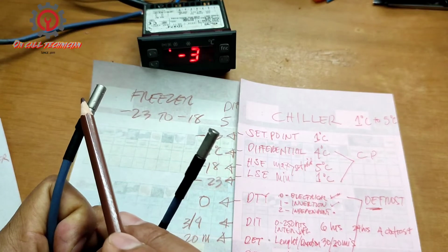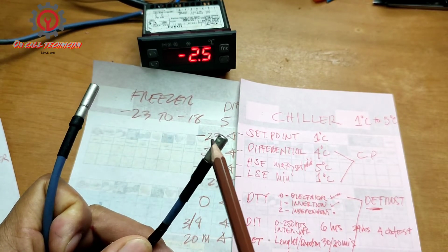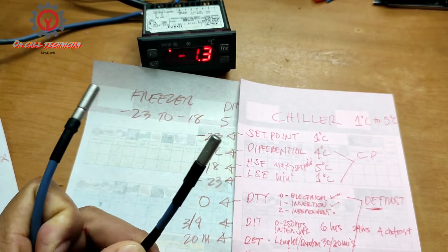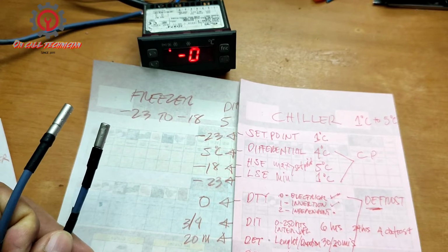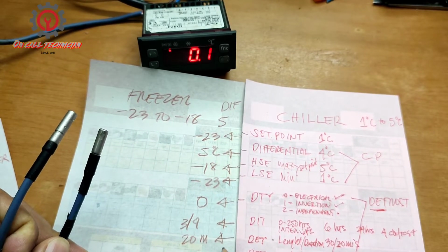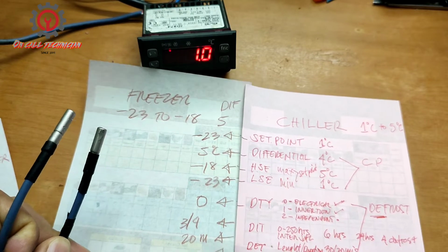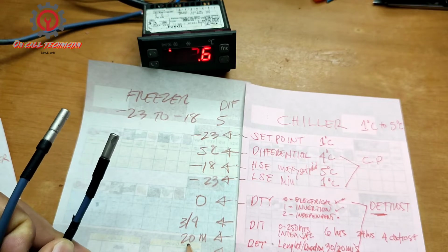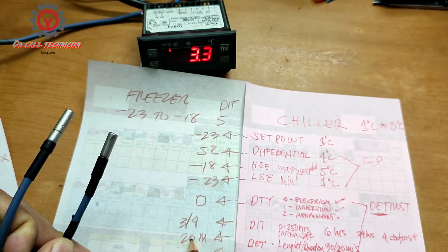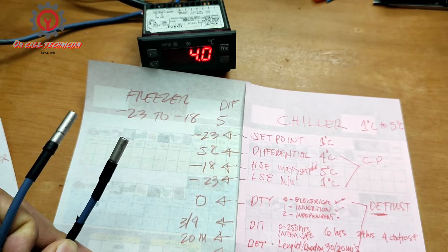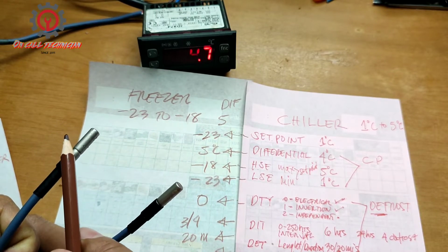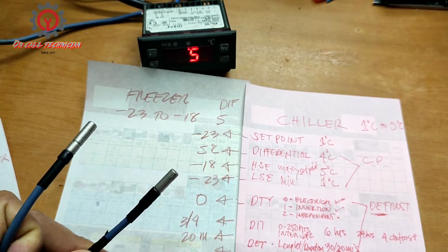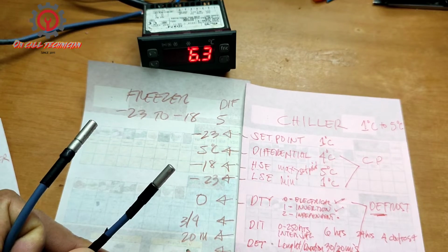One here is for the evaporator sensor, and the other one is for the room sensor. And this evaporator sensor is to measure the DST. The DST is the end of the defrost. For example, we put a value of 20 for the length of the defrost, and this 20 minutes counting will not happen once this evaporator sensor senses that the evaporator coil temperature is now 8 degrees Celsius. So we're going to put 8 degrees Celsius here.